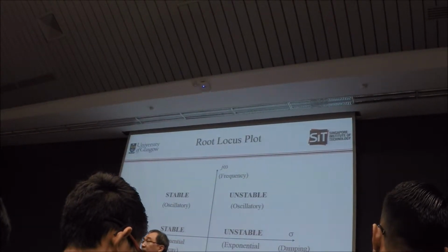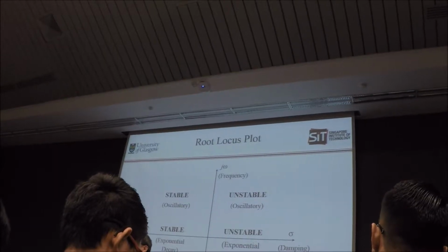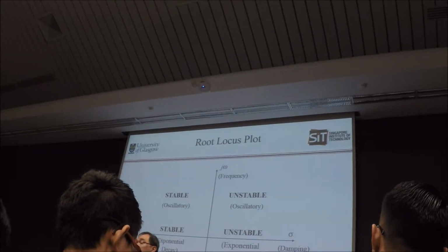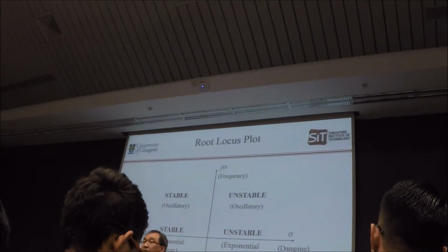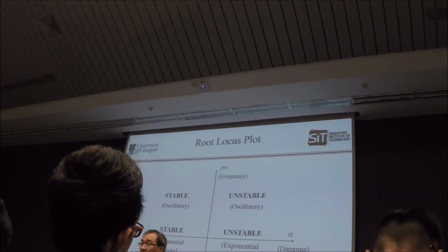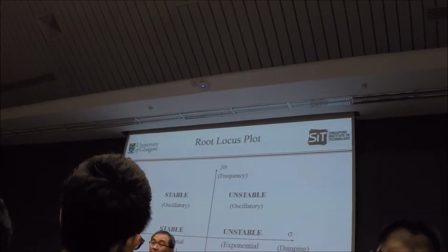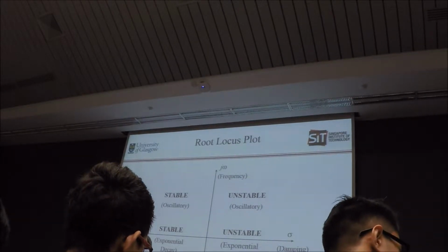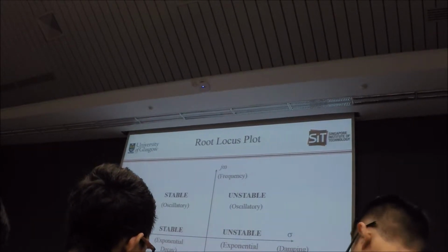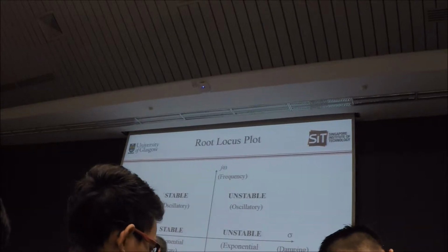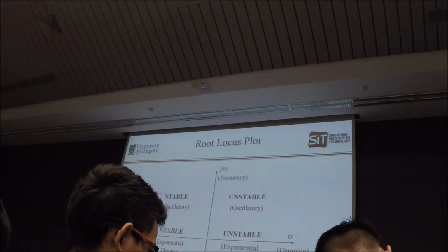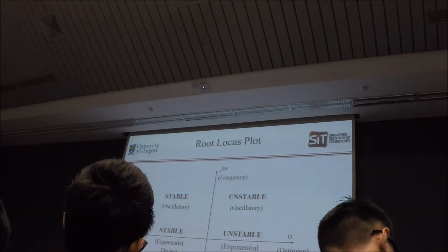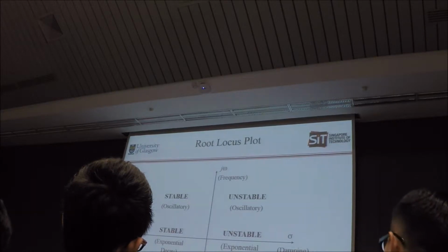Because using the Routh-Hurwitz, how do we do it? All you need to do is, based on the K value, work out one of the first column elements and set it equal to 0. That will enable us to work out the stability boundary. Am I correct to say that? If you have a standard transfer function that looks something like this,